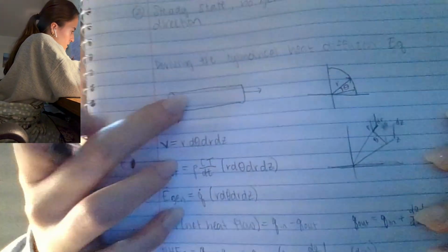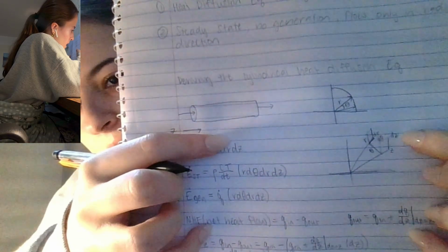I'm just going to flip to the next page for the net heat flow in the theta direction. That'll equal negative d q theta d theta times d theta again. So same procedure, negative d over d theta. Our q will be negative k. Now, since we're looking in the theta direction, we'll have the dz times dr for our cross-sectional area now. So dr dz times dT over d theta.